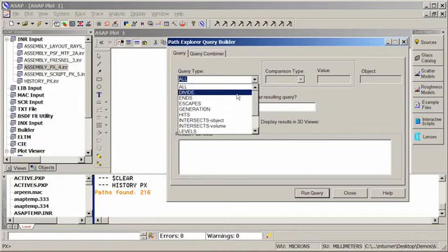For instance, I can go through and look for those rays that divide at a particular surface or object within ASAP. Similarly, I can look for rays that end on particular objects, or rays that escape the system. These would be rays that did not end on an absorbing surface. I can sort the rays by their generation. The 0th generation are the first rays that come from the original source, and then each level of splitting and/or scattering will create a subsequent generation.